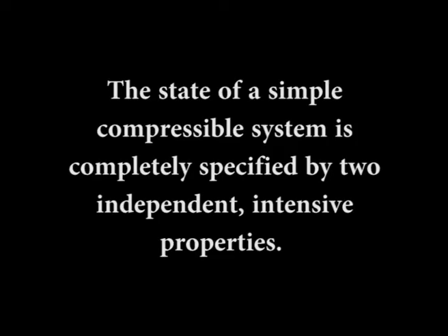The number of properties required to fix the state of a system is given by the state postulate. The state of a simple compressible system is completely specified by two independent intensive properties.